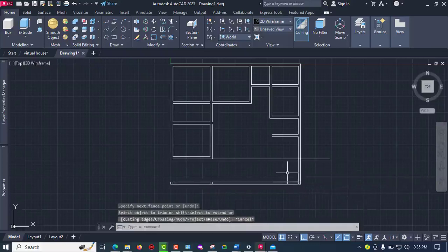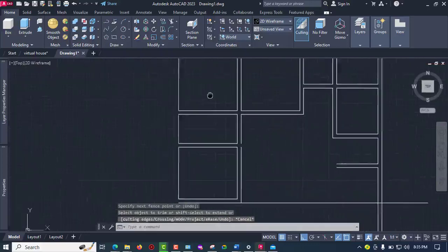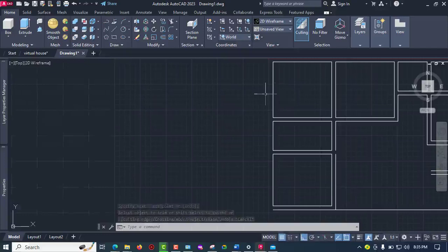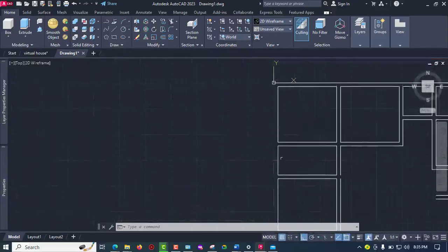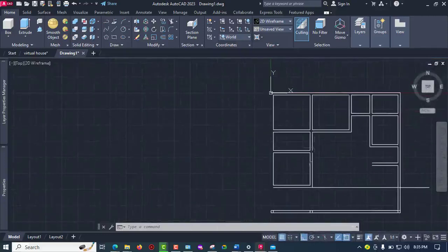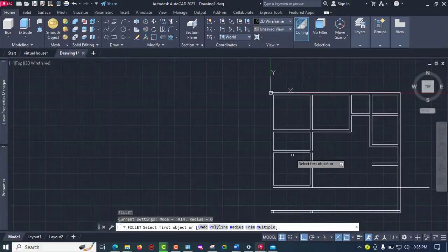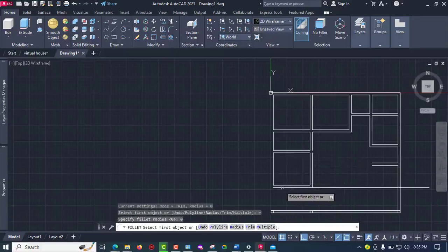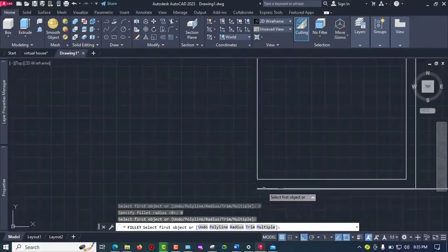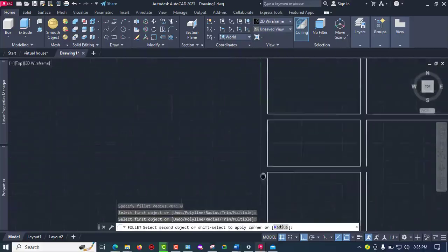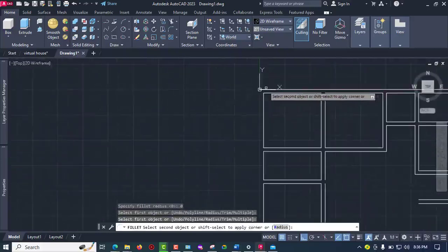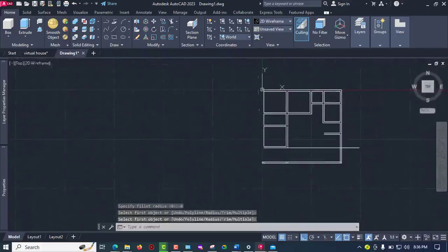Yeah, okay, now you can see that I accidentally deleted this line that is here that will make my wall, so I don't need to start creating another line. I'll still use my fillet tool. Radius 0. Click on this line. Let me zoom in so you can see what I'm doing. Click on this line, come here. Okay, it didn't work.